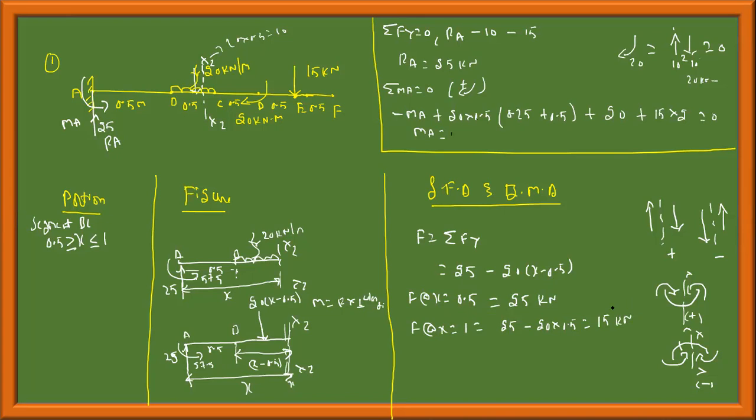Okay. Next, bending moment. Bending moment is the summation of moment about the section x. This is very important. The 25 force acting upwards from this section is causing a smiley-face bending, so the moment is 25 into x. Then there is a downward force, which we should also consider.